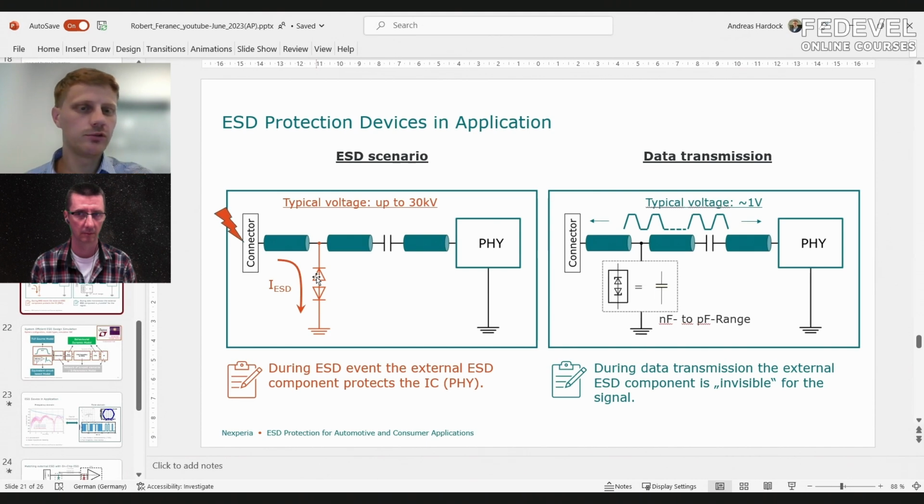We shoot a lot of pulses with increasing voltage and increasing currents, and we collect all this TLP data and put it in a behavioral model. We can do some modifications, some tuning of the model, and use it for ESD simulations. Even for the first case, you create an S-parameter model, but it's a different one.